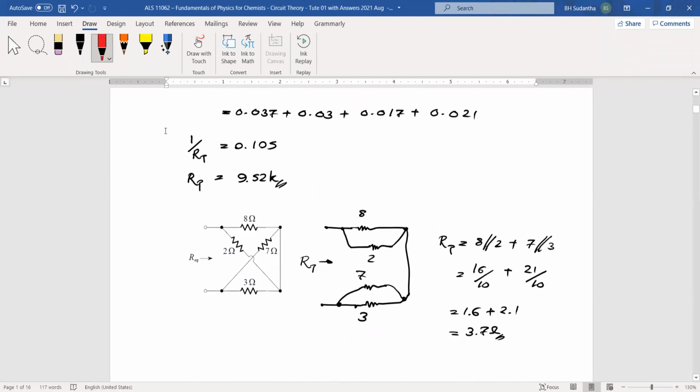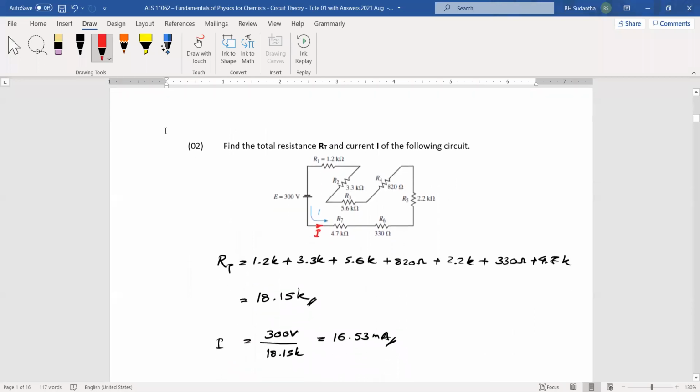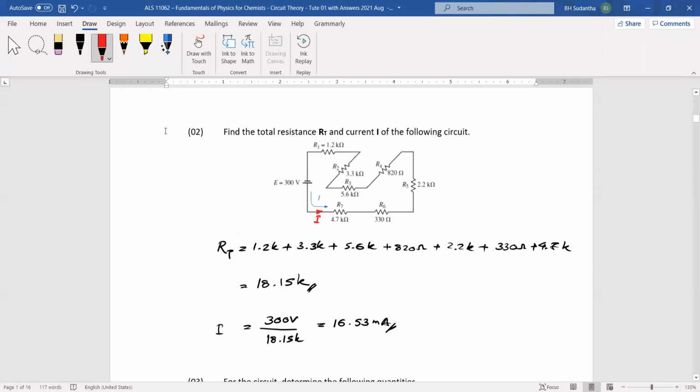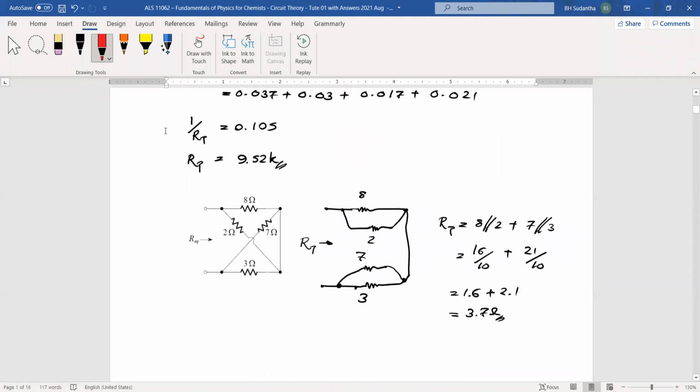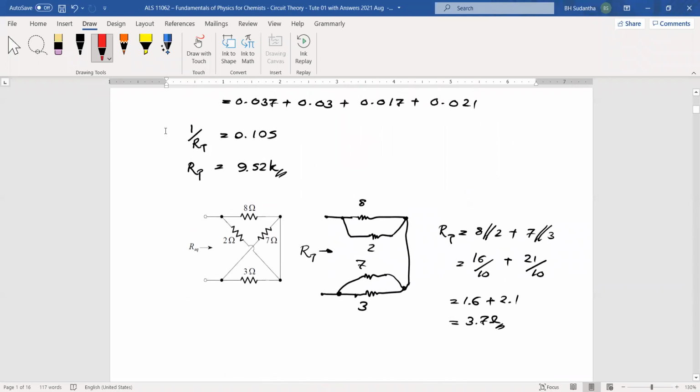So in the second one, not the one before this one, this one, aren't all the resistances parallel? No, here when you take this point, these two resistors are starting from those 2 points, and the other ends of those two resistors are connected by this wire. So simply, you can bring this point here.